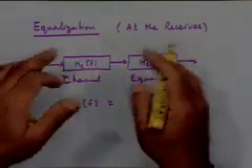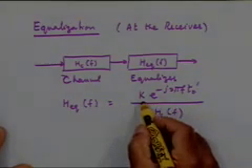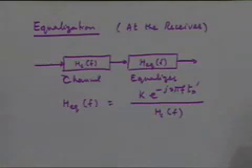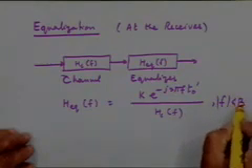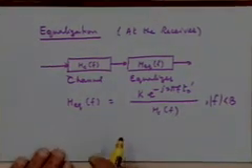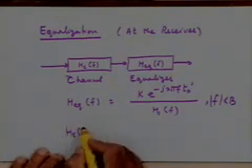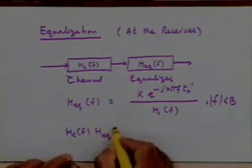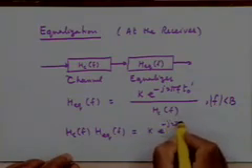The product is the net transfer function that the message will see, and it should be equal to k times e to the power minus j 2 pi f t0 prime, let's say some other value of propagation delay. Of course, this is required only for mod f less than the bandwidth. You can think of the product as an equivalent channel that satisfies the ideal characteristics.